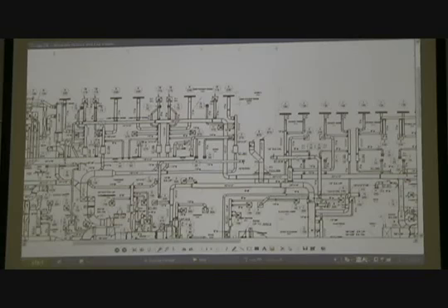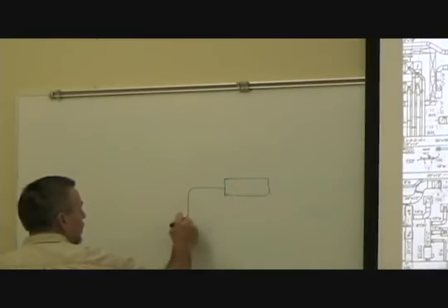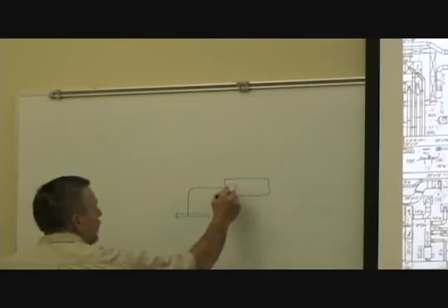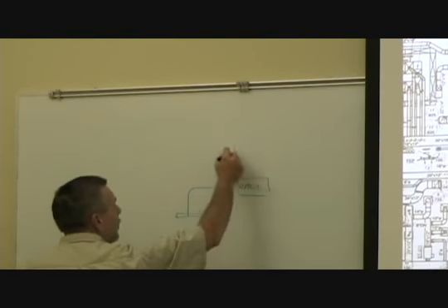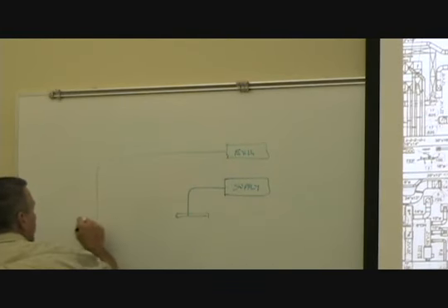Especially like in this OR right here, they might use an exhaust air terminal or return air terminal to balance the airflow to get a particular pressure relationship in the room. So instead of just a simple supply terminal coming into the room, you may have a supply terminal that comes to a diffuser, and an exhaust air terminal that comes over to